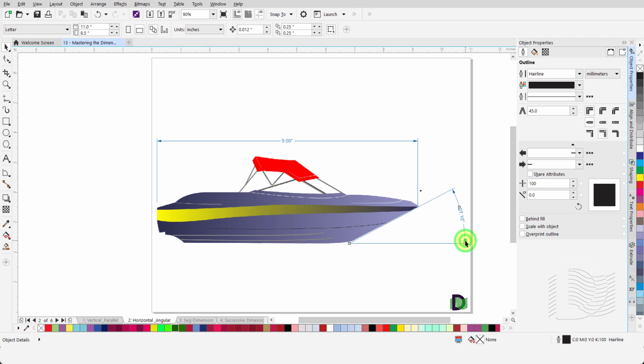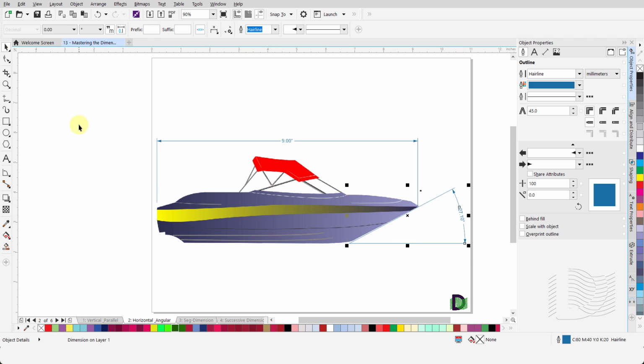Like I mentioned earlier, all the properties change options are common with the other dimension tools, except for the dimension unit. Degrees is the default setting for the Angular Dimension tool. But you can click on the black triangle to open the drop-down menu and choose to display the dimension with the word degrees. Or have the angular dimensions in radians or gradians.